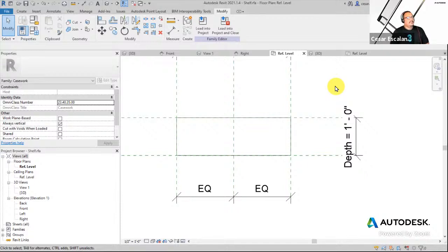In this exercise, they don't have the same insertion. For example, the pool is in a different work plane. It's going to be placed right in front of that. And so the insertion point is at the center of the pool, whereas the shelf, which we're looking at in floor plan, is the front reference plane at the center.